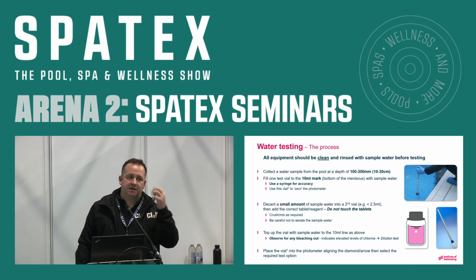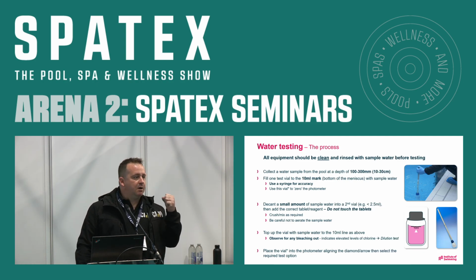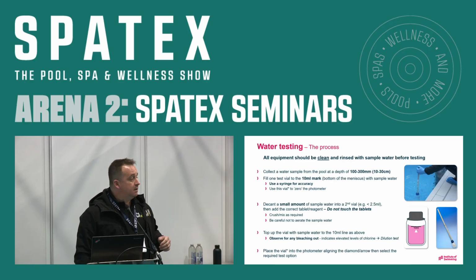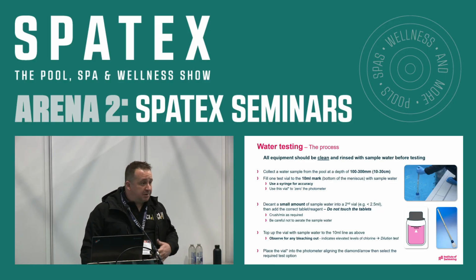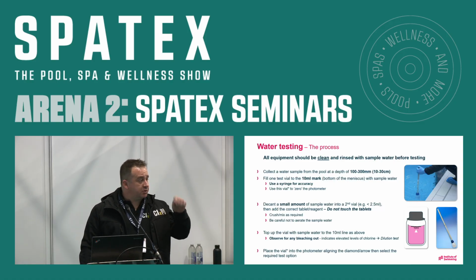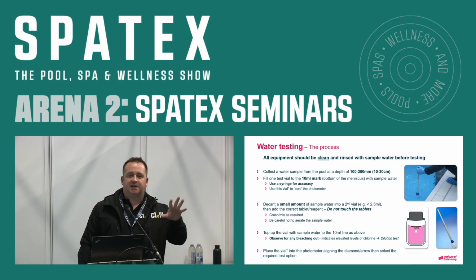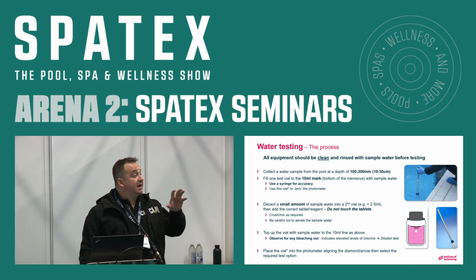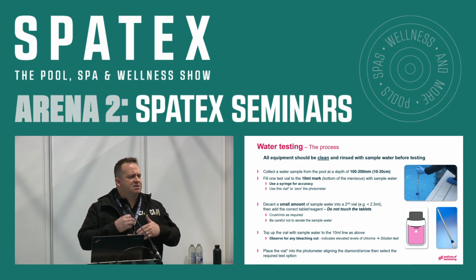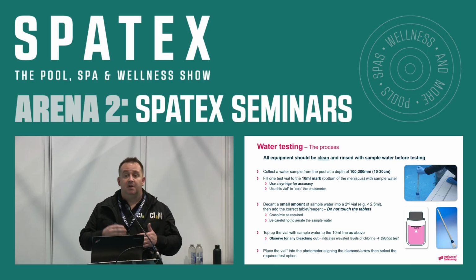If it goes pink and disappears again, all right, we have bleached the tablet out, okay? The chlorine level in the pool is too high. Yeah, and in the same way, if you get chlorine spilt in your clothes, it bleaches it out. The same thing happens to the tablet, okay? So a little bit of water first, crush, crush, crush, crush. Add the rest of it, look for the colour change. If you get the colour change and it stays pink, great. If not, we might have problems, okay? It's a warning, so you don't go to fix a problem which actually isn't there.